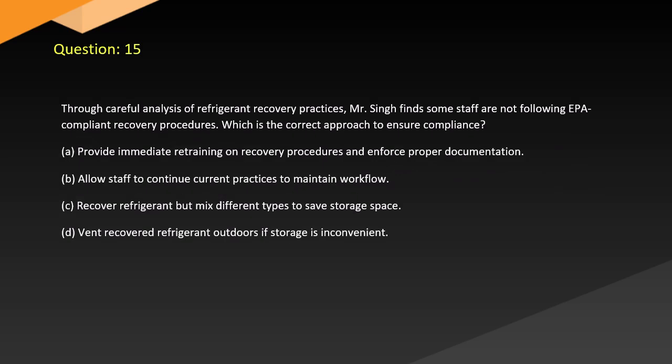Question 15. Through careful analysis of refrigerant recovery practices, Ms. Singh finds some staff are not following EPA-compliant recovery procedures. Which is the correct approach to ensure compliance? A. Provide immediate retraining on recovery procedures and enforce proper documentation. B. Allow staff to continue current practices to maintain workflow. C. Recover refrigerant but mix different types to save storage space. D. Vent recovered refrigerant outdoors if storage is inconvenient.